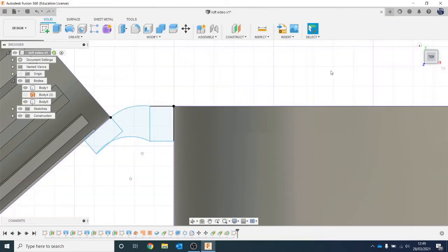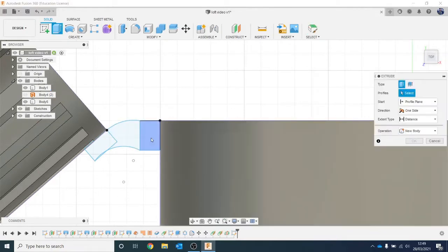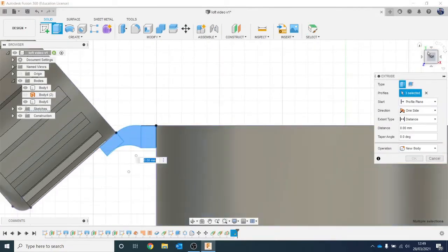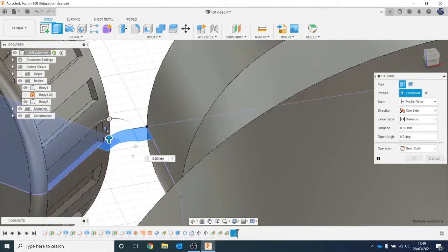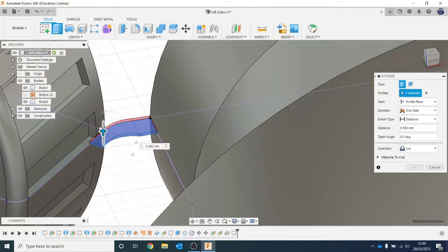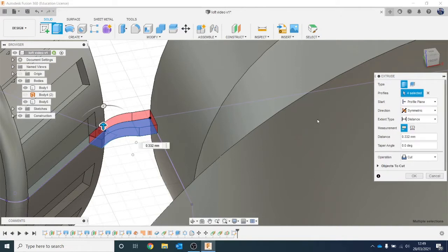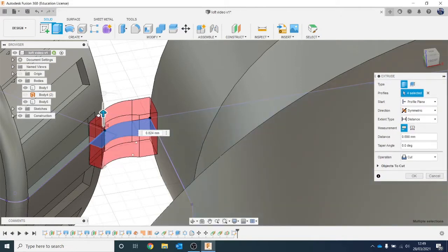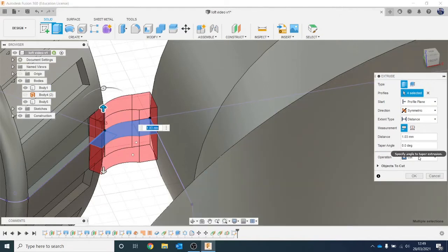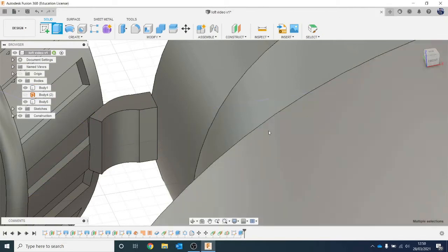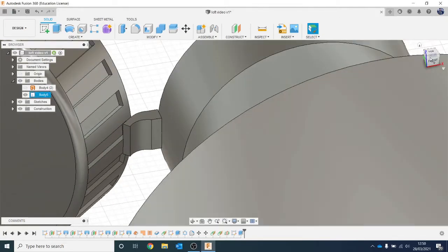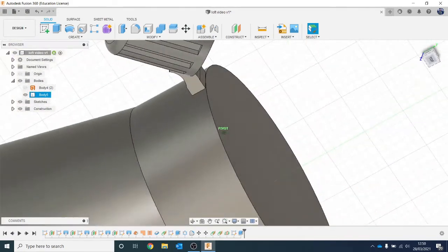So let's finish sketch. I'm going to hit E for extrude. I want to do those three profiles there. Rotate around so you can see that's right in the middle. So I'm going to drag up. Oh, I'll try that again. So I'm going to drag up. At the minute it's only going in one direction, so in the extrude menu I can change that to be symmetric, so it's going to be the same on both sides. I'll drag it up to about there, and rather than cut, let's do join, and hit OK, and you can see there now I've got a decent looking hinge.